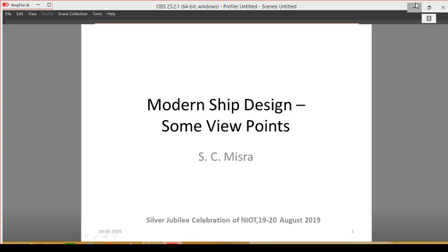This I am showing you, this is normally called design for production. Can I modularize the ship? Can I have rationalization of equipment? I will show you the next slide. You see, these are the variations that can come out of the slide I showed last. Please observe that not only does the forebody have 2 alternatives, the aft body is the same, and perhaps it could have the same engine also. So if this can be done, then you can imagine the time and cost overrun both will come down drastically. So this concept has been patented and it is available.